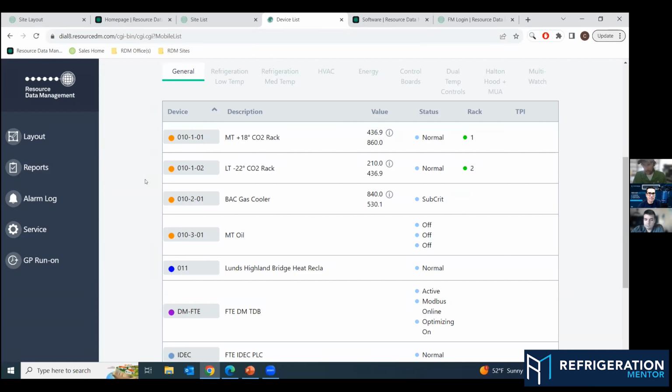I've noticed through testing and troubleshooting that we build a lot of frost with EEV/T settings versus EEV settings on the frozen cases. I'm guessing that's because of doors opening and closing, and our EEV/T setting operates off of temperature until it gets to superheat. And then it starts going off of superheat. So if that temperature's way up there, it's going to open that valve wide open and leave it there until it gets close to that superheat. And then it's going to start going off that.